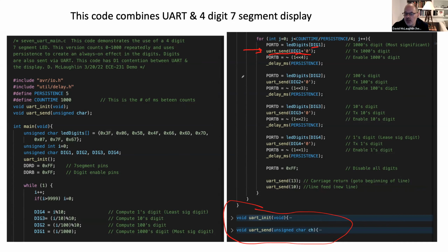And so we knew that we needed 8 segments to control this 7-segment display plus decimal point. So my suggestion was, well, let's use port D, because port D has pins 0 through 7. It has a full byte there. And so if they're shown in the red box, we've got 0, 1, 2, 3, 4, 5, 6, and 7. I mean, that's convenient. We have that whole port.